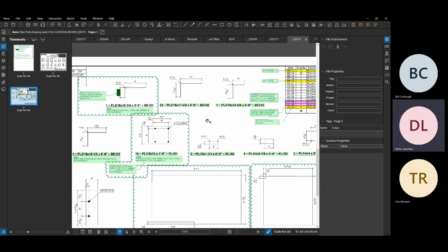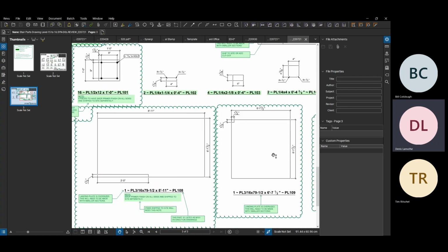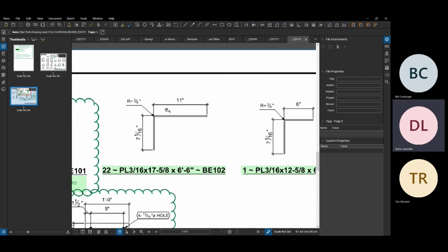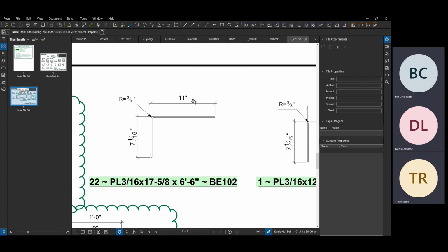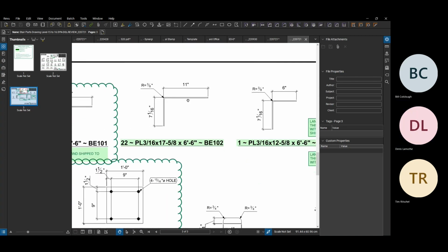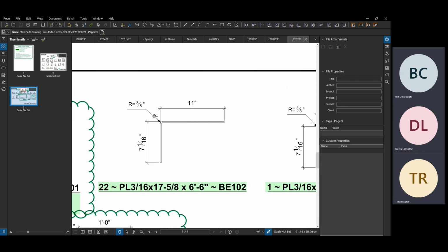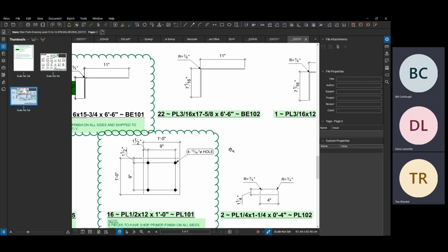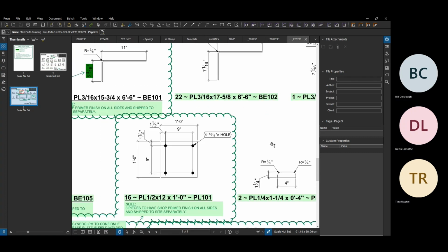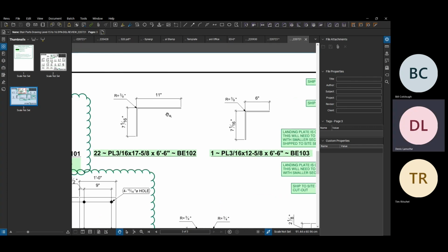So I think for the most part, we're shifting away from decimal places right now. We may come back to it later on, because I used to do part drawings myself with decimal places, but we've had some shops complain that their measuring tapes are in 16ths of an inch. What good is it to have decimal places? They can't measure it exactly like that. I kind of get where they were coming from. The decimal was just more for me, so that when you add things up, you didn't have too much dimensional creepage going on that would throw off your overall dimension. Hopefully that answers your question.